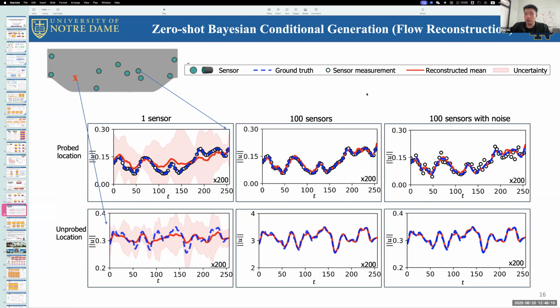For the strategy of selecting the locations, I would recommend that one observe the flow field first and identify which part or location in the flow field has distinct flow vortex pattern changes going on, which will have a very unique signal reflecting this flow evolution. And I will typically choose those locations as the conditional locations, especially for sensor reconstruction tasks.